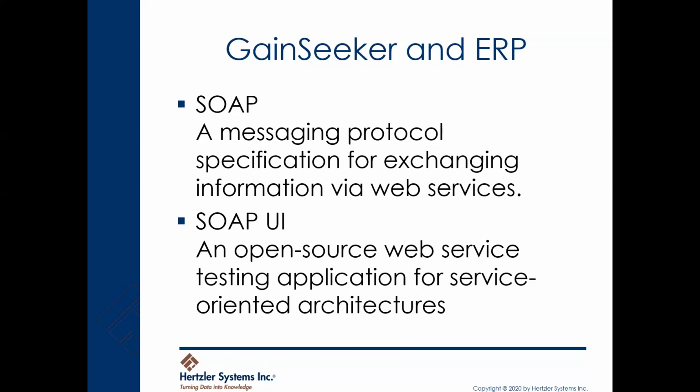I think of this a lot as being similar to HyperTerminal when you're trying to test communications with a gauge via RS-232. This allows you, without even GainSeeker in the loop, to quickly and easily say, if I send this command to the device, what response am I getting back? Or if I press that button on the gauge, what response am I getting back through RS-232 protocols?